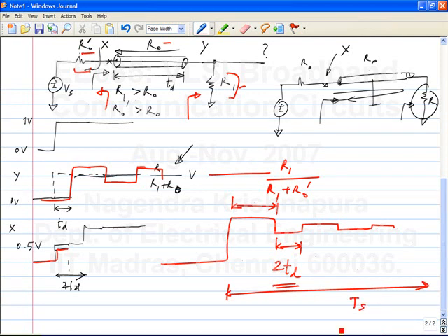You note that this always happens, right? Whenever you just connect a wire between 2 points, this always happens. But usually the effect is masked because, for instance, in the low speed experiments that you run in the lab, this TS is much more than the time of flight delay. But if it becomes closer to the delay, then you will have problems. So for instance, if your TS was only this much, you can see that there is significant effect well beyond TS.